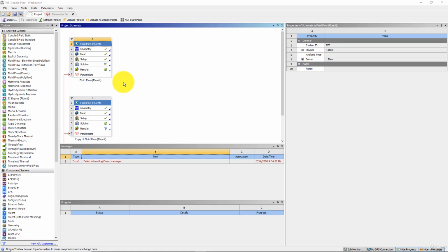With increasing number of nodes, maybe you are decreasing the discretization error, but at the same time you are increasing round-off errors. So the mesh refinement should be up to a level so that with successive mesh refinement we don't see any change in the result. That's the goal of the mesh independence.